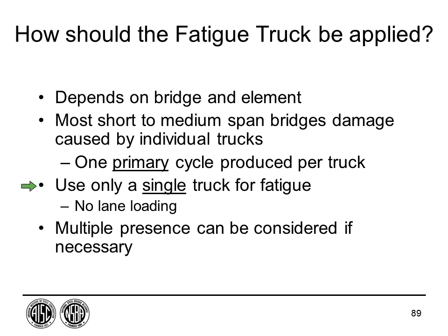This is also very important. In strength design, you would load all conceivable lanes. Not for fatigue. For fatigue, we only load a single truck. And we put it in each lane, but individually to check different locations. That's because it's the day in and day out type loading. There is no lane load either. If you recall from the discussion on loads, you have the truck portion of the load. And then remember there's that distributed lane load in the HL93 strength load. We don't include that portion. It's only the truck itself. Again, it's attempting to be as representative of day in and day out traffic.